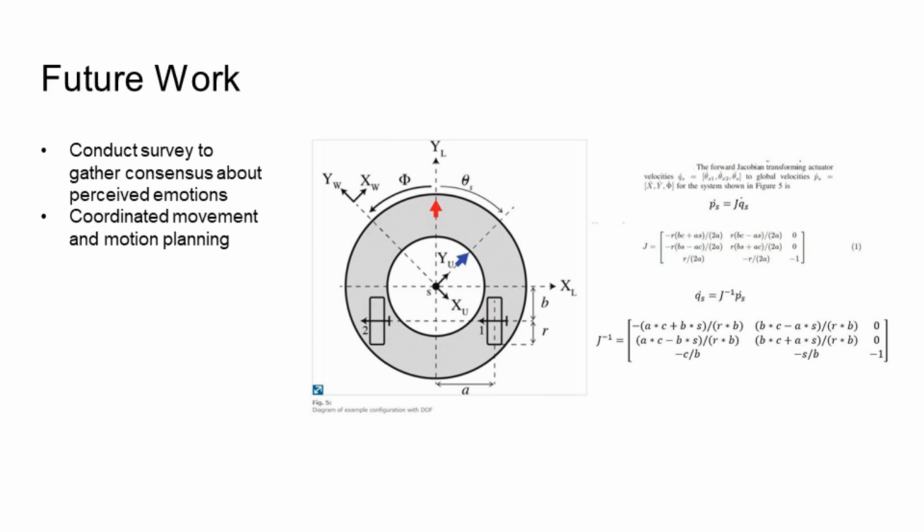Additionally, although we have precise control over Quori's upper body motions, our control of Quori's wheels and movement is currently limited. We plan to implement a differential drive controller based on the Jacobian to coordinate the base and turret motors to achieve omnidirectional capability, and eventually develop coordinated motions such as facing a given point in space while moving.